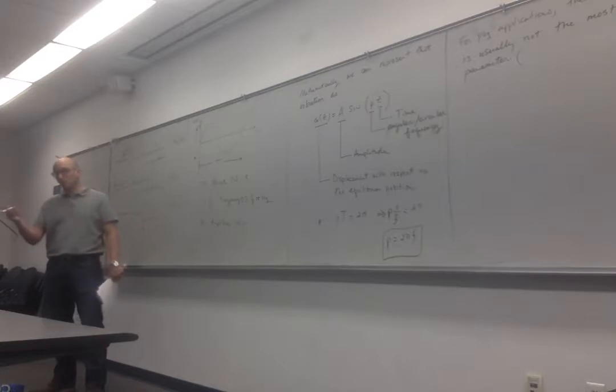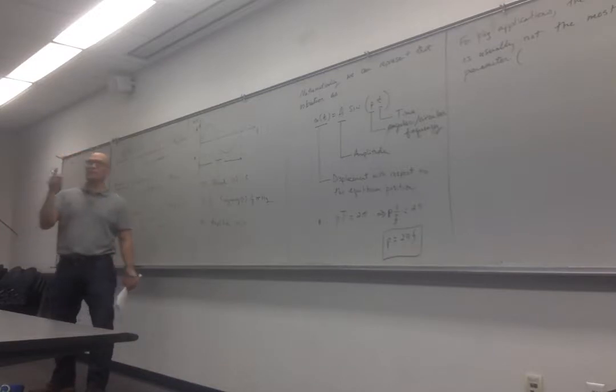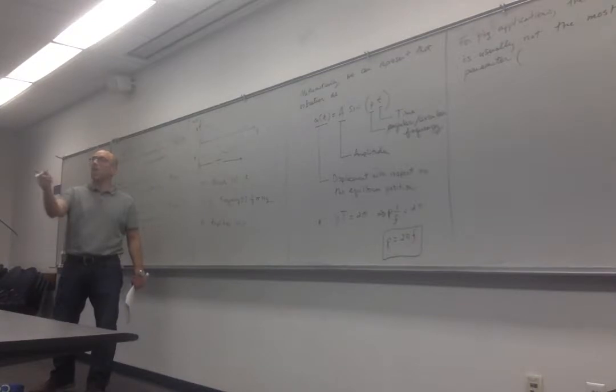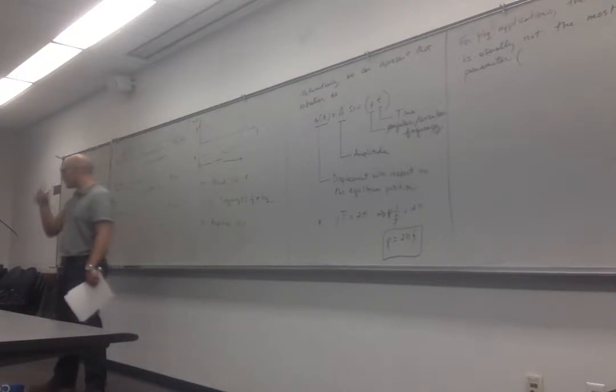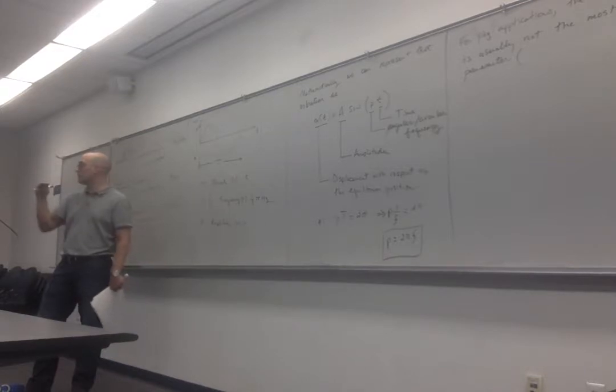But the cushion, by being there, influences the behavior when you expose the product to vibration. What did you say again? When the cushion, when it throws. Okay, good, that's what you said. It's similar, but that will happen on an impact. When you have vibration, what you don't want is for the amplitude to be so large that the cushion bottoms out.